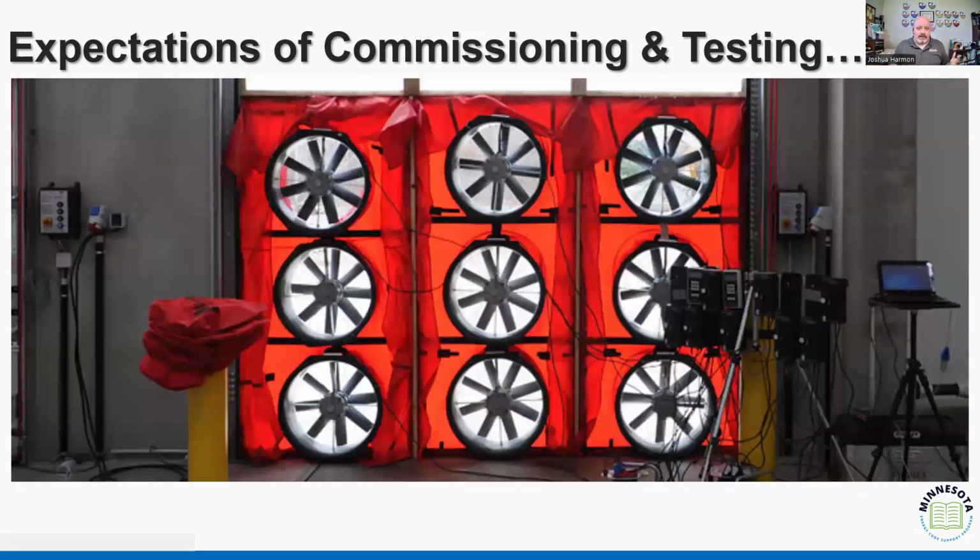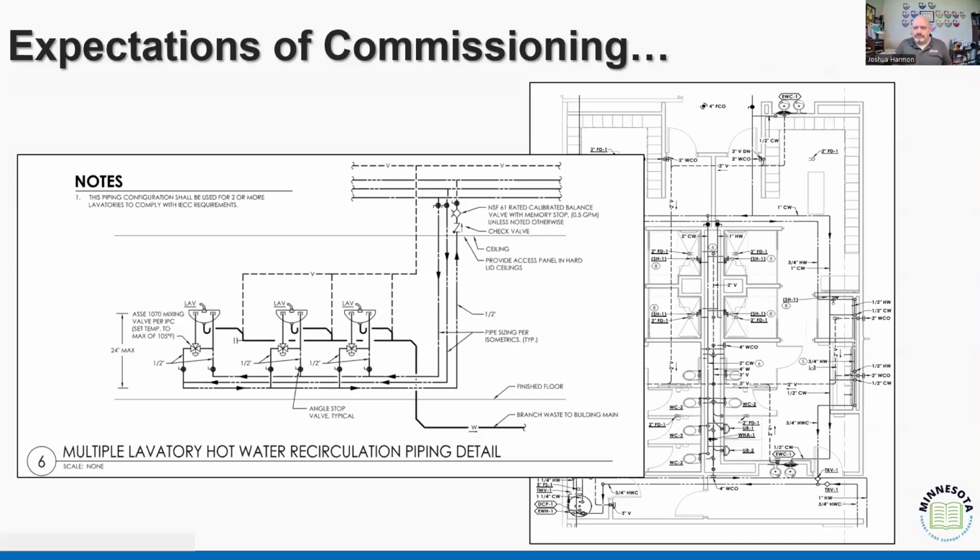This is a heated warehouse space with a loading door, right? So we're going to install a series of fans. We're pressurizing that building to make sure, one, that the envelope is properly installed, and then also the duct distribution system is properly sealed and connected. But that's not just enough to just do the mechanical.